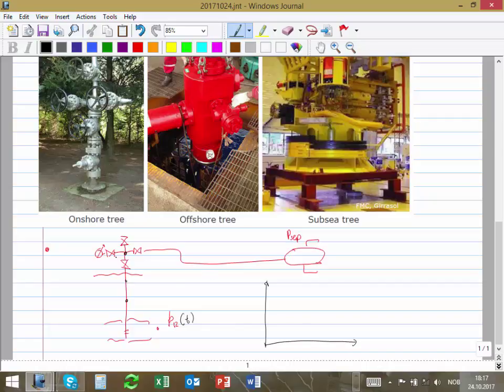If we say, for example, here at the wellhead, PWH versus Q, how does it look? Going down, yes? If I start producing more and more rate, then the frictional losses in the tubing, or the pressure drop in the tubing, will be more and more, and then it will start going down. And that one I calculate from here all the way to here.